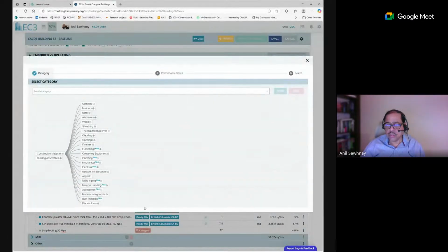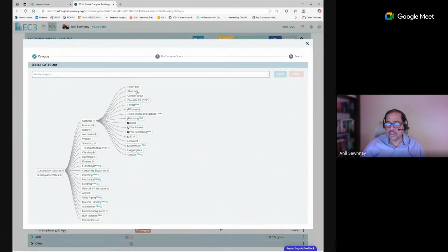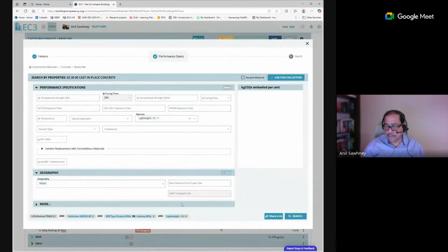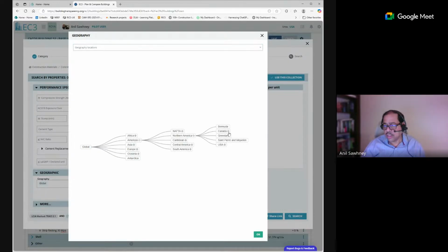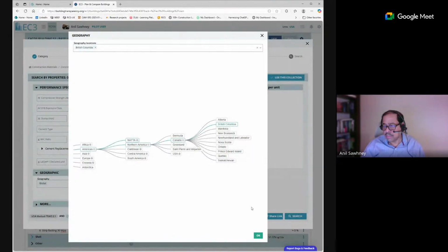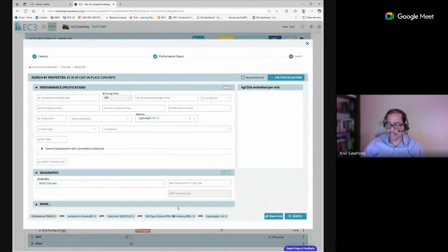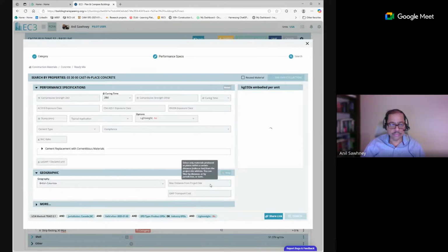So I click on category, click on concrete, click on ready mix concrete, look for EPDs, set the location, Americas, North America, Canada, British Columbia, click OK, and then search.